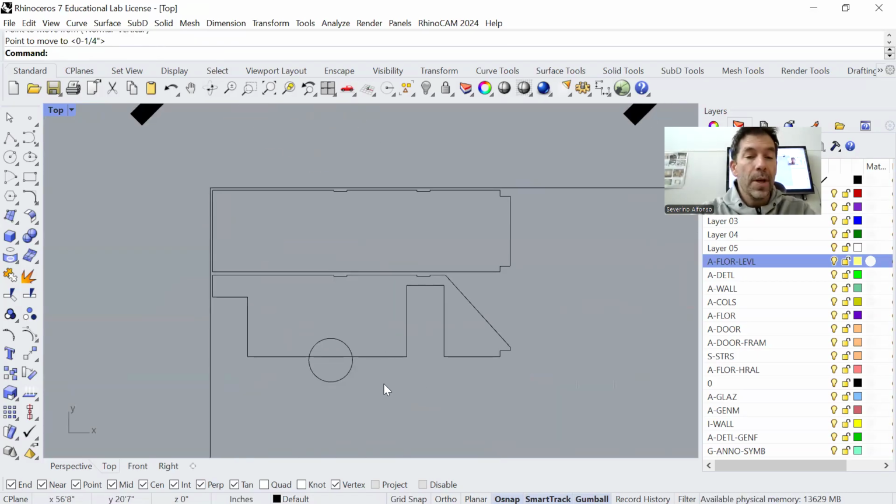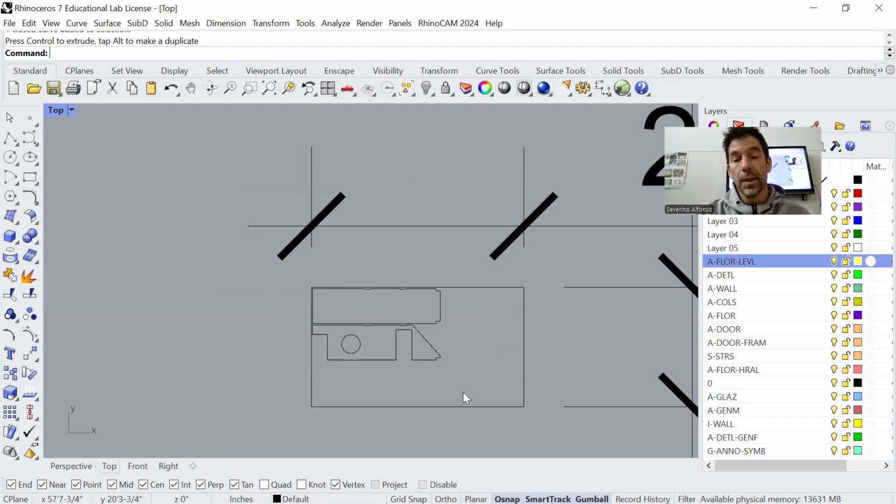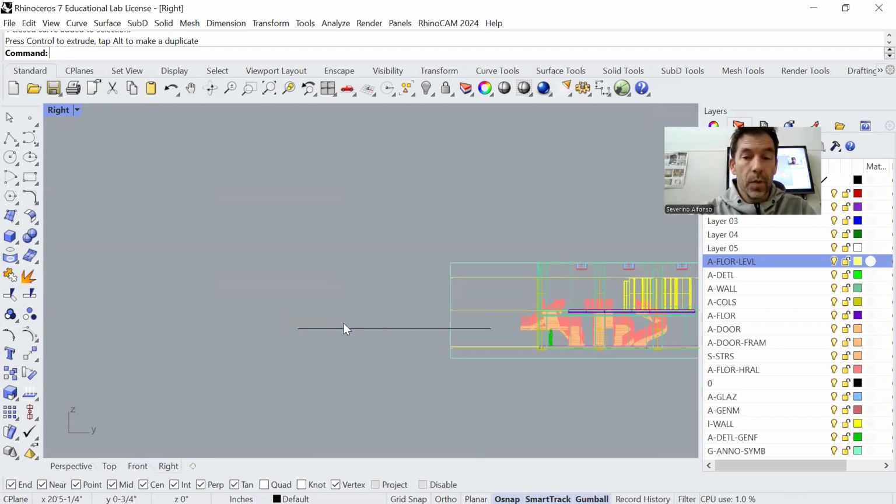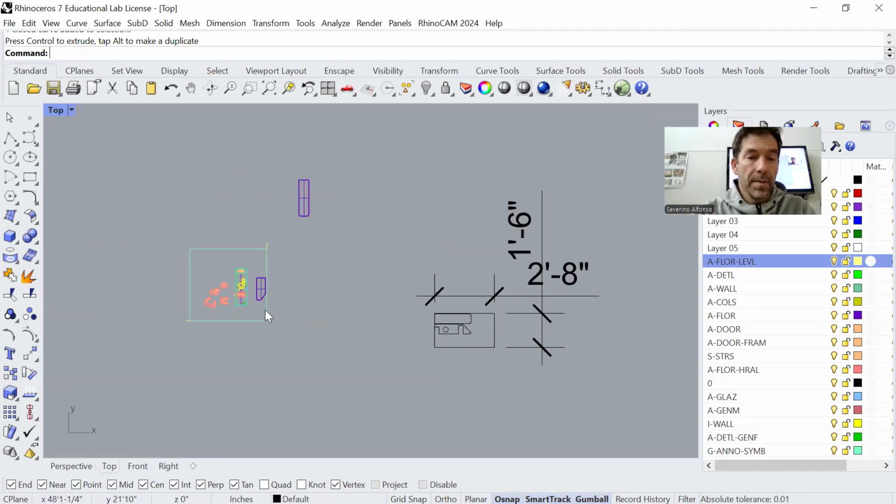So there's a bit of a distance between each of the cuts, because when the laser cutting goes through, especially in some materials that are thicker, it burns. So it's creating this kind of a shadowy quality. So just keep some distances in that sense. Okay, so just continue that thought.